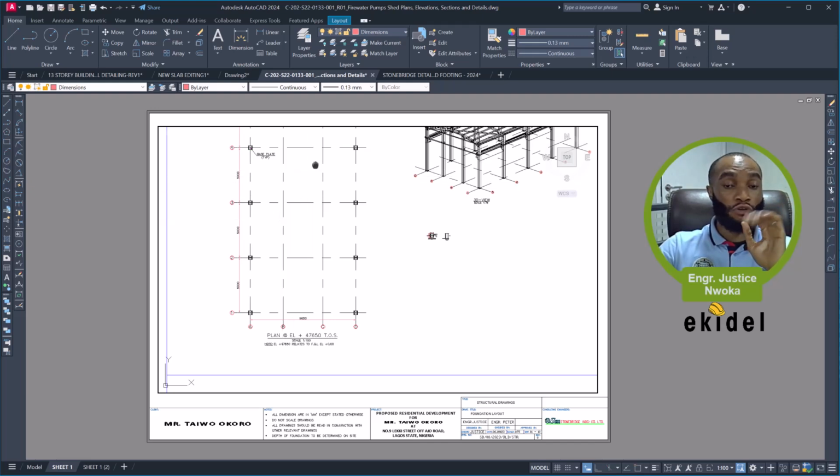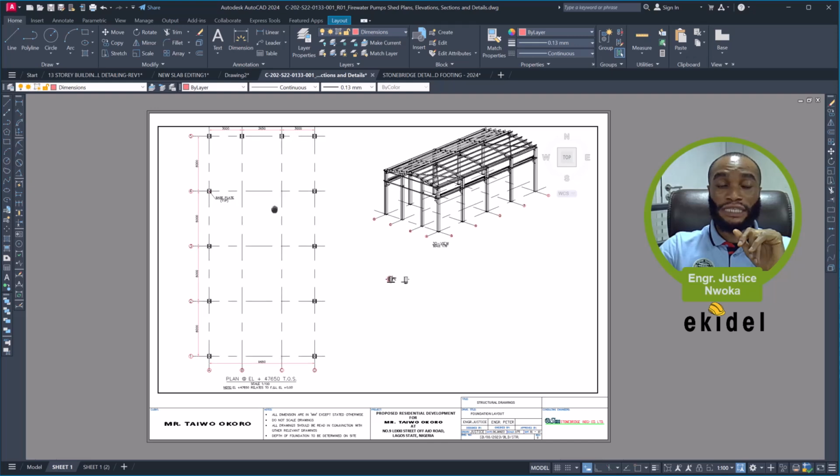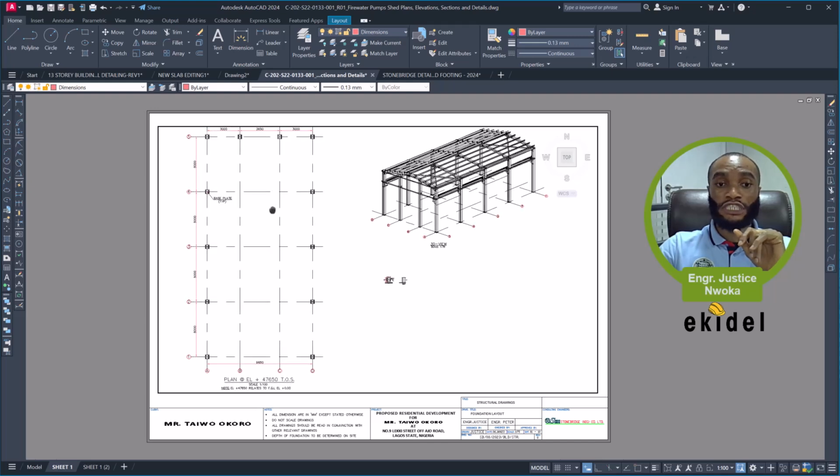Don't zoom. After you're done typing the scale factor and pressing SP, don't zoom again, just pan, because once you zoom, you have removed the scale you set for that drawing. So just pan to fit your drawing in the viewport, which in this case is the 1:100 one.